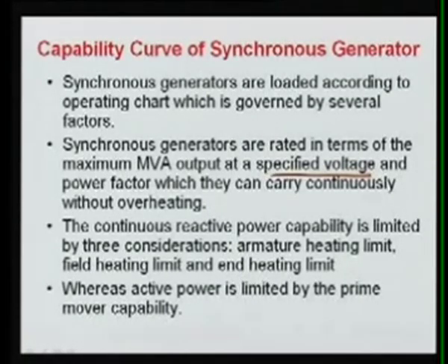of all its components, and it should not violate the various operating limits of the synchronous generator. The continuous reactive power capability is limited by 3 considerations, and all these 3 are basically heating limits. The first is the armature heating limit, the second is the field heating limit, and the third is the end heating limit.